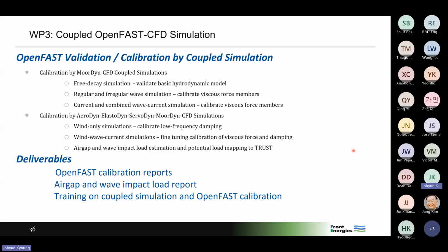I would treat them as two. The whole integrated loads to structural analysis, including hydrodynamic loads, not CFD based but potential flow strip theory, will be covered under OC7. And then I would say that the FE wave CFD solution has already been quite validated. Work package 3 is really about checking the coupling to OpenFAST and making sure that we believe that it's robust.